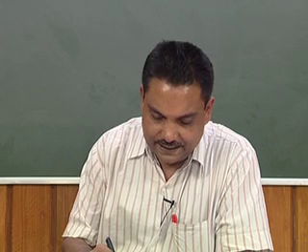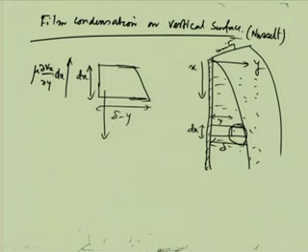Here we have some other forces. One is rho L g into delta minus y into dx, which is nothing but the weight of the liquid trying to come down.